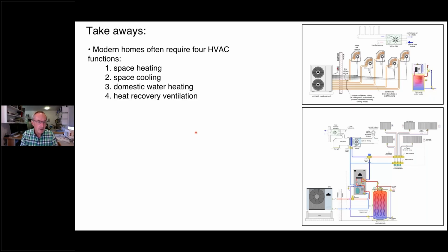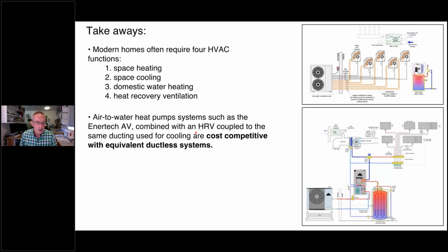So I've included it in our system design: air-to-water heat pumps, such as the Enertech AV, combined with a heat recovery ventilator. And when you're using the same ducting for cooling and heat recovery or ventilation, it's cost competitive with equivalent ductless systems. And by equivalent ductless systems, I mean the ductless heat pump combined with a separate system for ventilation, heat recovery ventilation, and a separate heat pump water heater for domestic hot water.